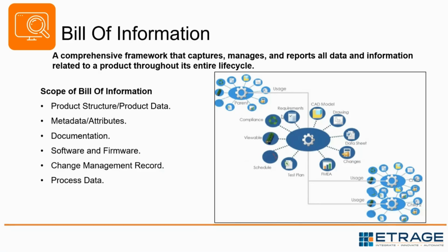The other benefit is that it streamlines the release process or the revision process of the information. Instead of managing individual components when it comes to release and revision, you just use one action to release and revise. Because when I'm revising this WT part, I can simply go in and say, collect automatically for me all the related data to my product. And then it will fetch all the related CAD, drawings, and documents. If there's any software linked to this product, it will also collect that information as well.